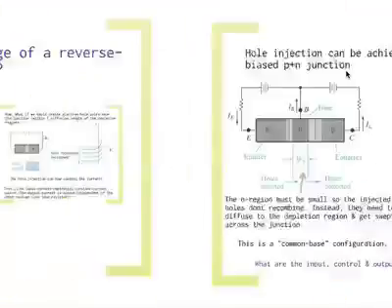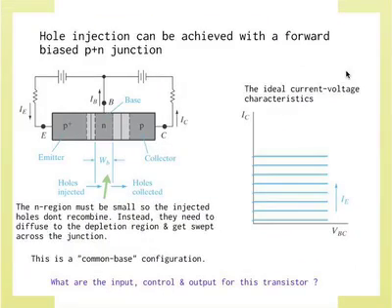In a bipolar junction transistor, of course, the whole current injection comes off because you have a forward bias PN junction. Injection is a majority carrier injection in a forward bias PN junction. To review, the structure looks like that. This part on the right hand side is the reverse bias PN junction, the collector base, which is reverse biased under normal operation.